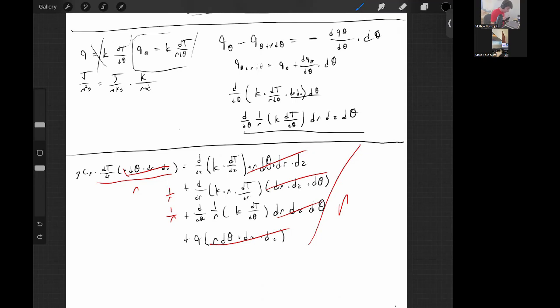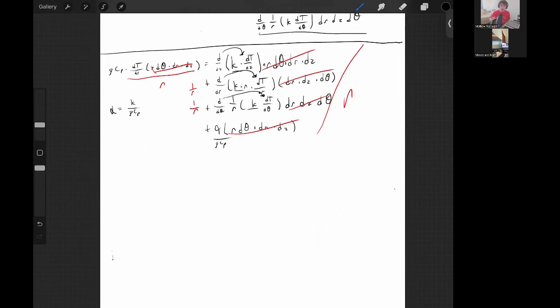So, okay. We've made that, which is nice. The other thing that we can do is we can actually get our heat diffusivity constant by saying that our heat diffusivity constant equals K over some density and heat capacity, right? If we look, we have K here, and K here. And now the last thing I'm going to do to try to simplify this is I'm going to go ahead and shove these differential terms over here and just make them double thetas in this case. So I'm going to divide by density and heat capacity. So now that we have all of these simplifications, now what we can do is shove them together.